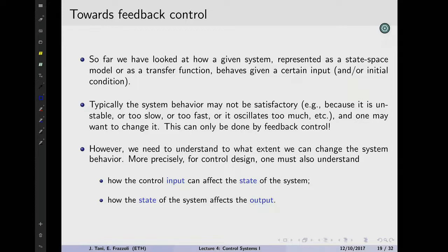But that is a mathematical solution that will never work in practice because we never have a perfect knowledge of the math of what's going on. The models are always wrong. They're always simplified descriptions of the physics, so this perfect cancellation doesn't work out. But then we introduced feedback, and feedback was a little bit more magical idea of, let's not just send in a signal and choose the signal in a fancy way such that we get what we want as an output of the system, but let's measure the output of the system and literally do some operation with the reference signal. For example, check how distant, so a reference signal is where we want to be.